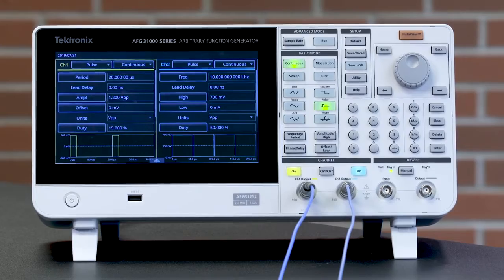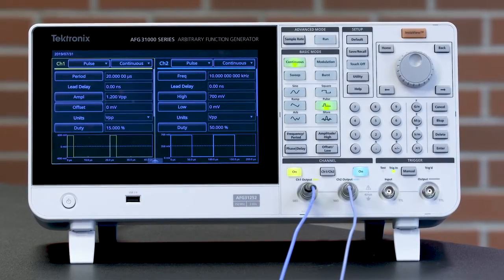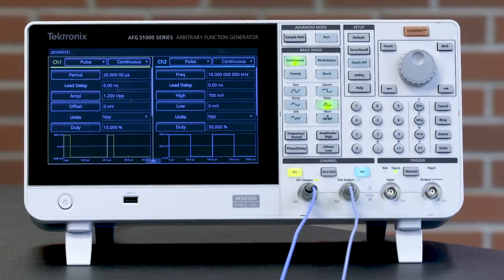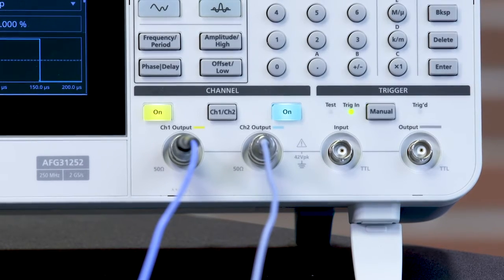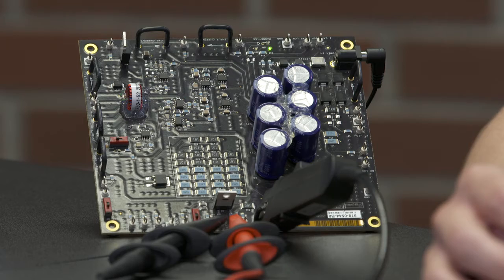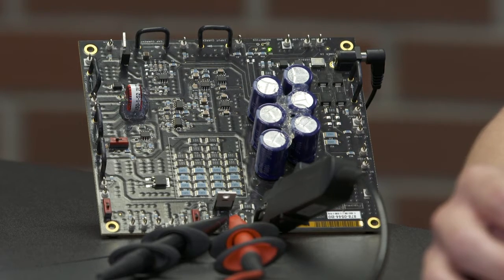It's also quite common to activate the switches using an external AFG, such as this AFG31000 with isolated outputs, when the drive circuit is not verified. We don't have that issue here, so we're just going to use the drive circuit on the board.